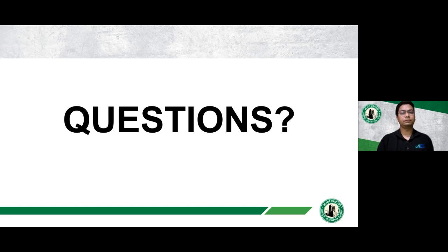This is a question from John. You mentioned that you can't get the size of rebar using GPR. Is there any non-destructive technique that could give you an estimate of a rebar size? Yes, there are cover meters. You place it on the concrete, and as long as you place it right over the rebar location, it can estimate the probable size of the rebar. So yes, we have cover meters.